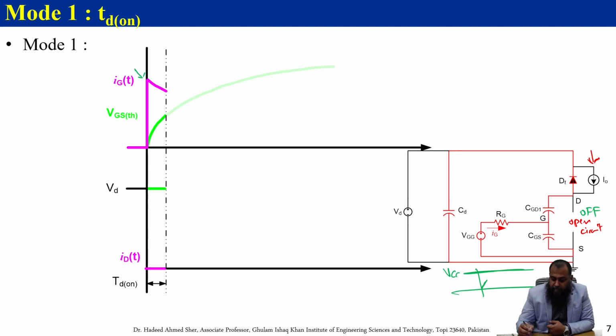Later, the current going here will bifurcate into these two capacitances, and it will have its route something like this. At this particular point, this current and this I naught will combine and use this freewheeling diode system, after which the current which was flowing through CGD1 will flow through this side, come back here, and have its complete circuit here.